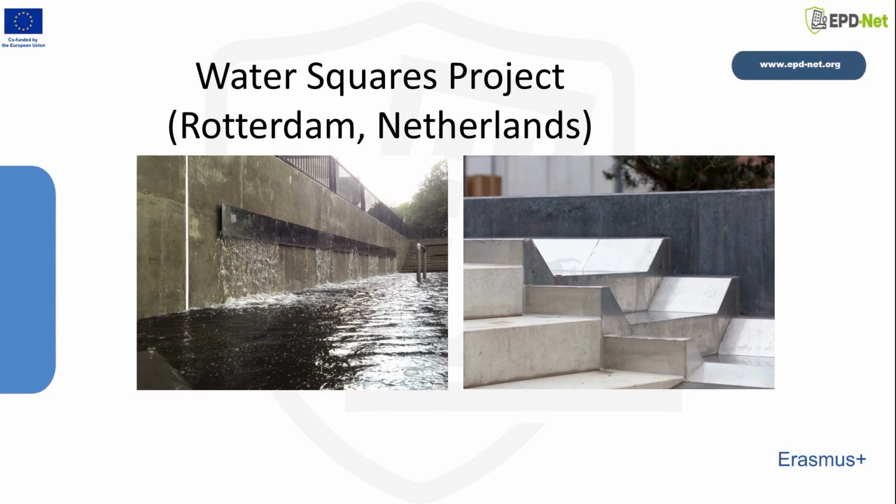Three basins are used to collect rainwater. One deeper basin only receives water when it rains constantly, while two shallow basins for the adjacent area receive water anytime it rains. Here, the water is gathered from the square's surrounding bigger area. Rainwater that falls on the square enters the basins through sizable gutters made of stainless steel. These locations are suitable for anyone on wheels and anyone who wishes to observe them in action while the weather is dry. The deep basin is both a theater to see and be seen and a real sports pit.